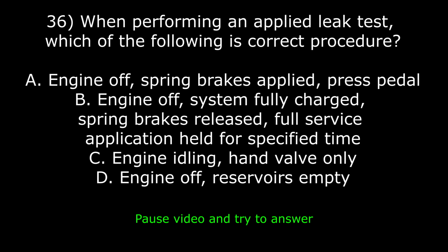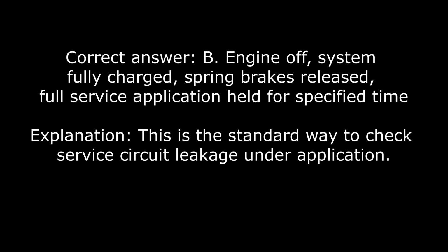C. Engine idling, hand valve only. D. Engine off, reservoirs empty. Correct answer B. Engine off, system fully charged, spring brakes released, full service application held for specified time. Explanation: this is the standard way to check service circuit leakage under application.